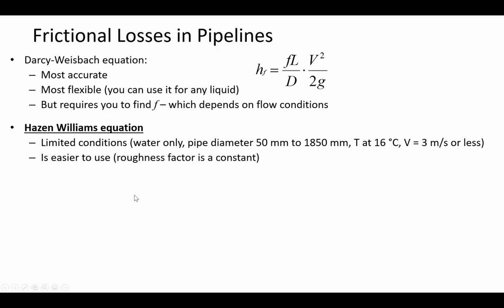The Hazen-Williams equation can't handle anything, but it's pretty good for typical conditions in a drinking water distribution network. And so the water that flows through the pipes underground to get water to your house, usually water is flowing through pipes that's within this range of diameter.